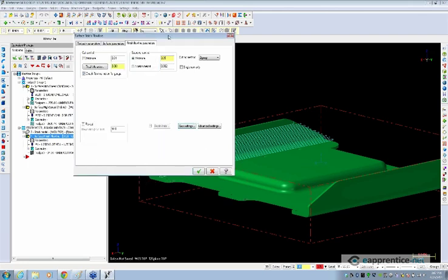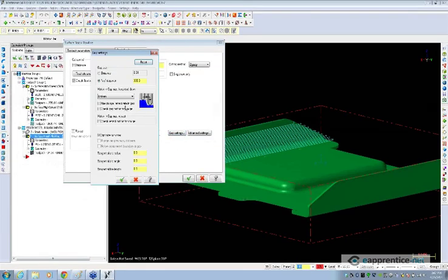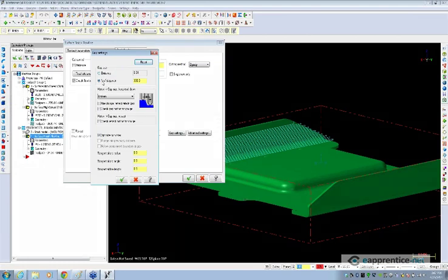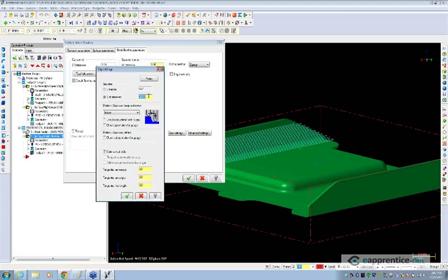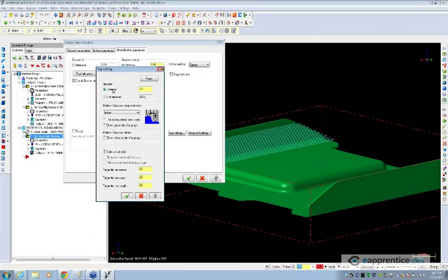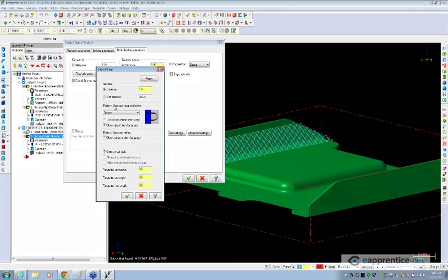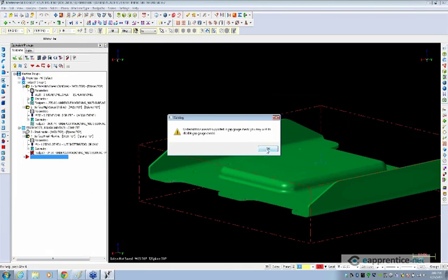And that's actually what's causing this little retract motion right here. This distance happens to be greater than whatever our gap size definition is. Right now, it's a percentage of our step over, 300%. Our step over is 50 thousandths, so our gap size is about 0.15 inches. I'm going to instead set our gap size to a physical distance, in this case 1 inch. So we'll do a 1 inch gap size, set the gap motion to smooth, and then I'll regenerate.